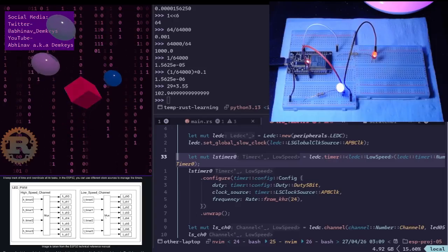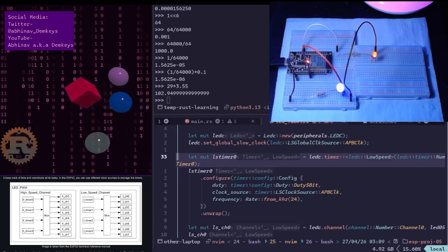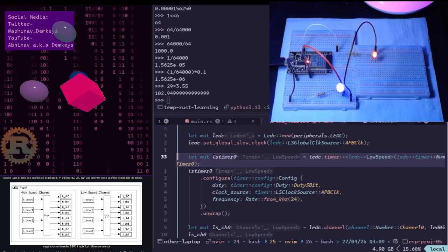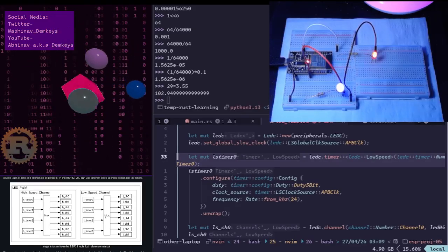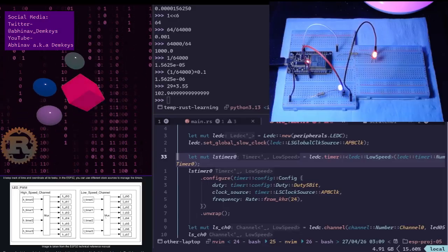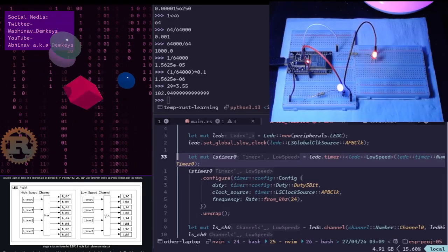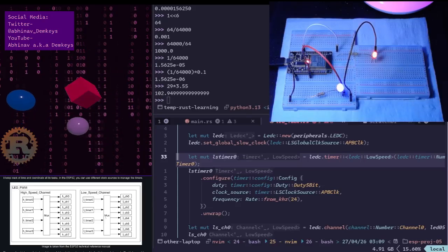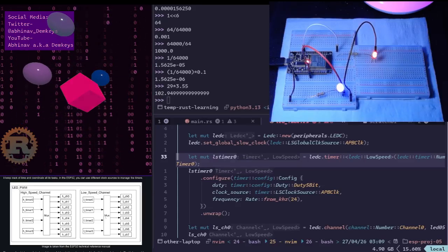Peripheral limitations. On many ESP32 variants, the slow clock is physically muxed or connected primarily to the APB clock for stability. While the hardware can sometimes use the RC fast clock, which is the internal oscillator, that clock is often too unstable for precise PWM without calibration.